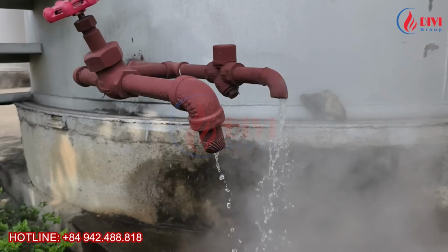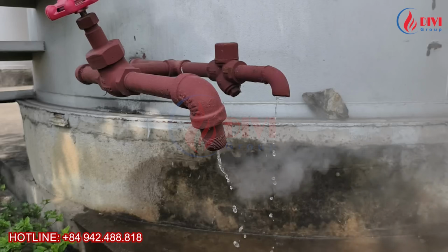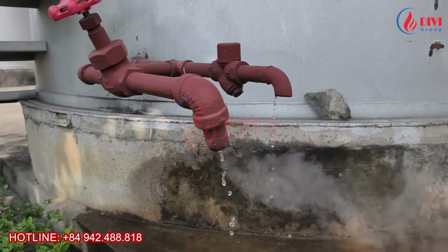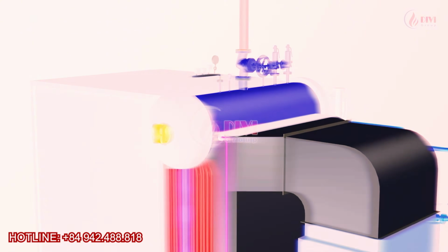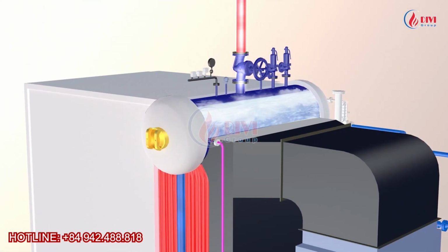In terms of steam generation speed, this design has an advantage over the combined water tube and fire tube boiler. However, when it comes to steam dryness, a two-drum water tube boiler may produce wetter steam if an effective moisture separation system is not incorporated into the design. That's because the upper steam drum is usually smaller, providing less steam space. During rapid load changes, water droplets are more likely to be carried into the steam flow.